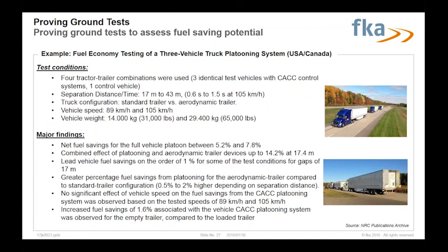And on this test, I like that they have combined the platooning system with aerodynamic trailers. What they could see is that they even have a greater percentage fuel saving for platooning for the aerodynamic trailer compared to standard trailer configuration. This was 0.5% to 2% higher, depending on the separating distance.